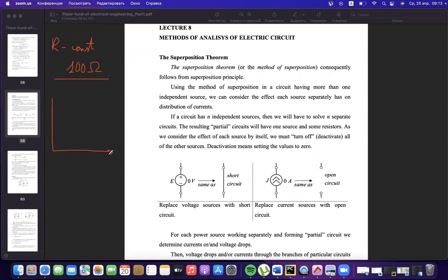It means that the volt-ampere characteristic of that element, the dependence between applied voltage and applied current that arises from Ohm's law, should be a linear function, just a straight line. Because if resistivity is constant, then as much as you increase voltage, at the same rate you increase current. That is why this situation is called a linear element.